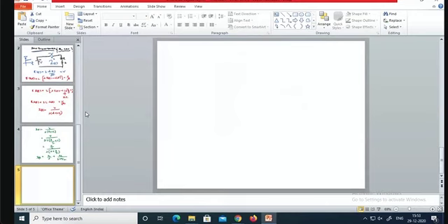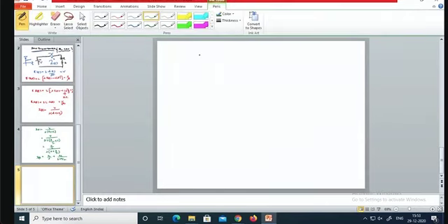Then you can take the Laplace inverse later. So if you solve for K1, you will get it as V by R. This is at S is equal to 0. And you can solve for K2, this is equal to minus V by R. This is when S is equal to minus R by L. Because the roots of the equations are 0 and minus R by L. Okay. So now just substitute those things in the standard expression.